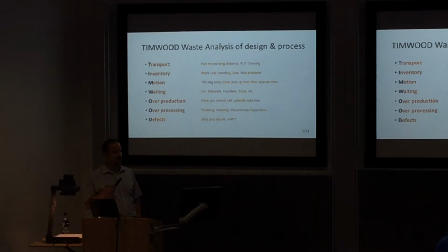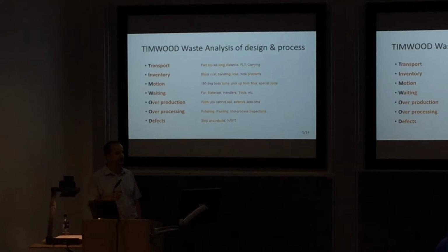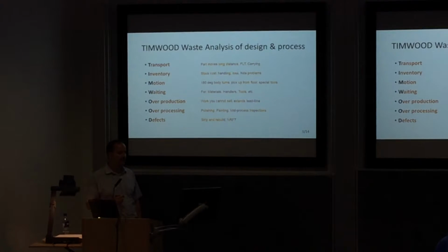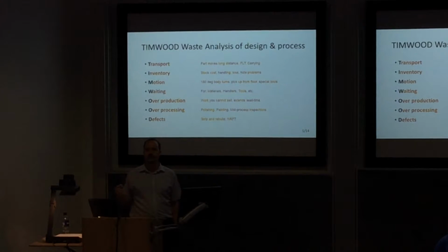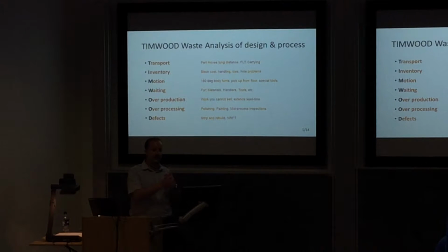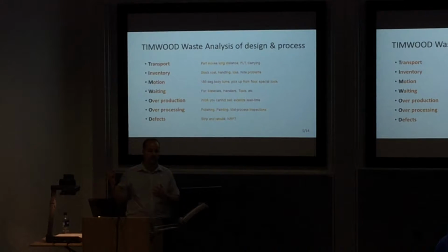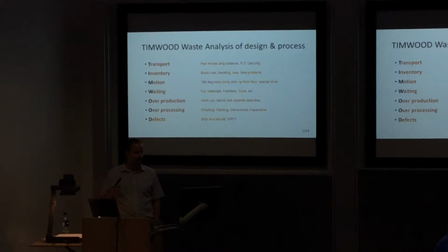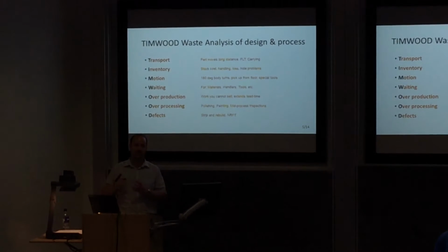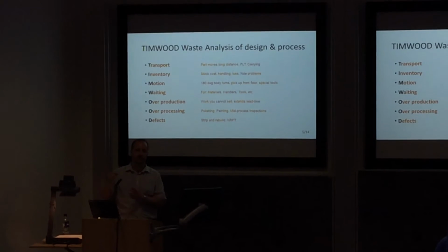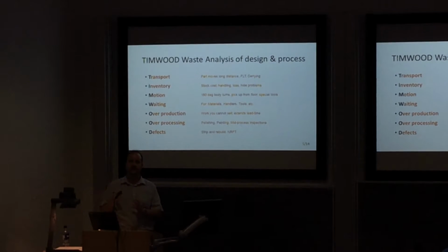The way to think about it, if you look at the T from TIMWOOD, the transport, are you moving the parts a long distance? Are we buying parts from the Far East that could be bought locally or vice versa, depending on where that's manufactured? When you look at inventory, we all now recognise that manufacturing large volumes of parts and holding them in stock is not good practice for manufacturing industry.